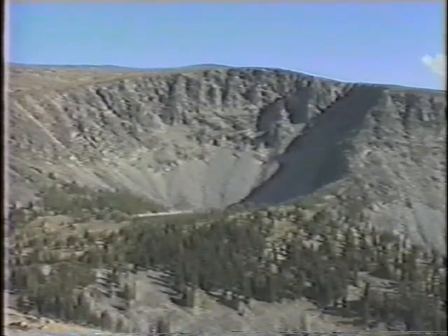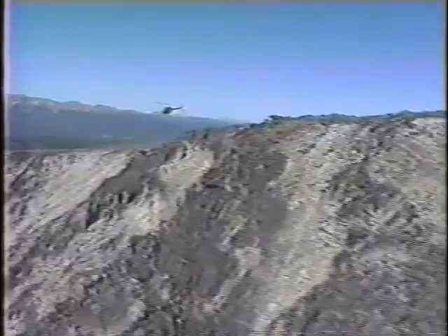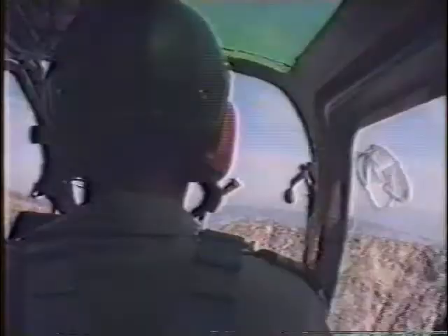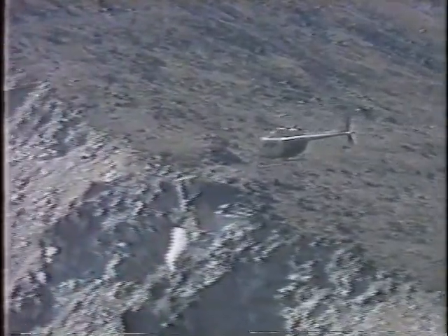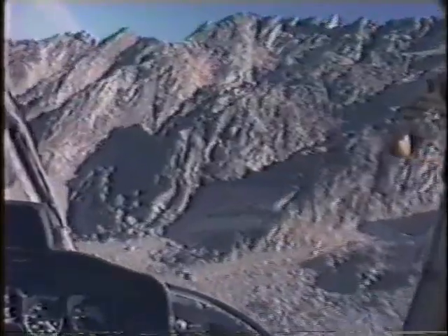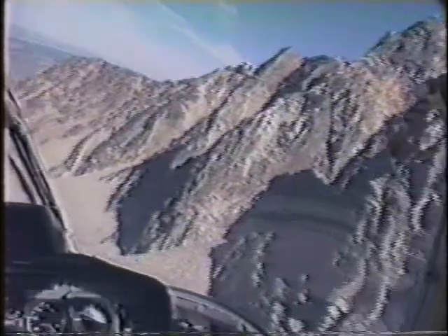If you really want to try landing in a cirque, first check your blood pressure and temperature, then the sun and the boundary layer to see if it's possible. Then, work your way down, starting with a recce around the rim at 40 knots, trying to stay in the good air, and then progressively lower recces of about 300 feet each time,